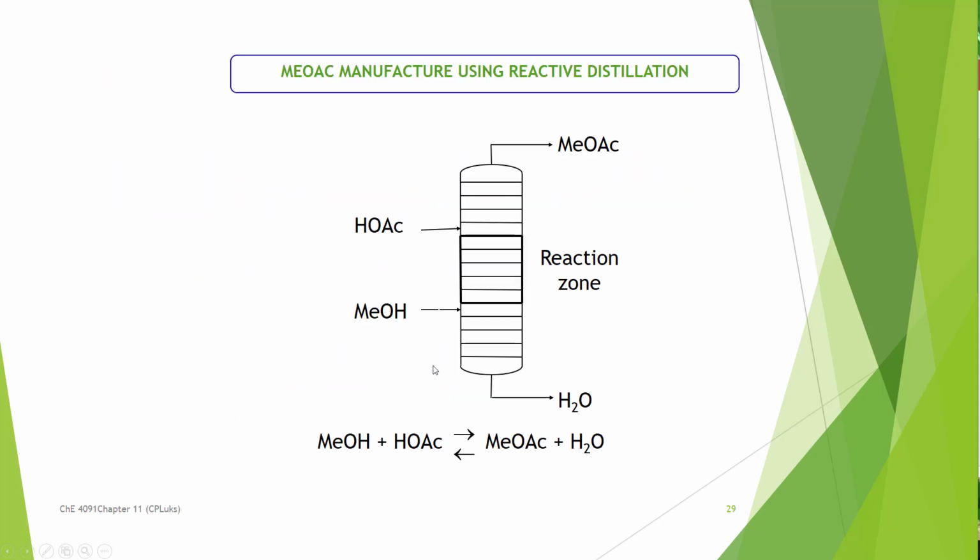We bring in our materials and we have a reaction zone, but whatever's left over will go out the top. This will hopefully all react away, and then just the water leaving. So I've got my product and my feed streams reacting, and I end up pushing my reaction more towards completion than equilibrium conditions would have predicted.